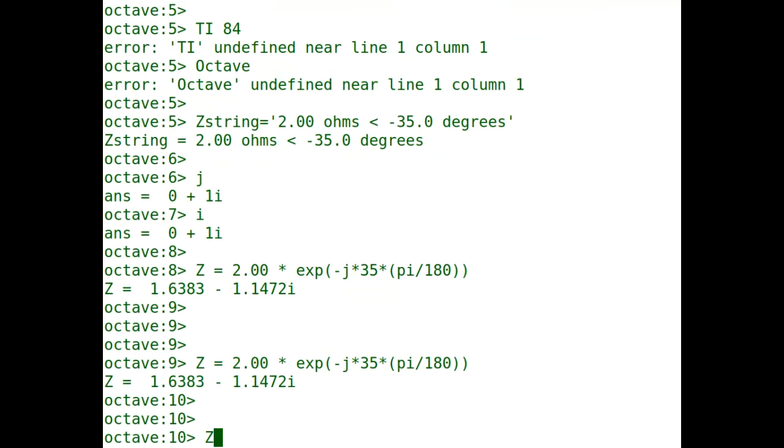And so remember that Z is equal to R plus J times a positive X of L minus X of C. And since this is negative, as I said before, then there is no X of L. Or at least if there is, what we're getting is there's less capacitive than there is inductance. And so what we're doing is just getting the X of C.